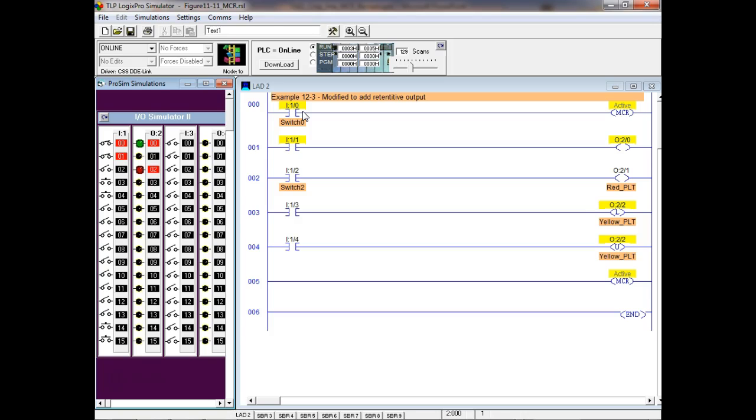So normally, if we're going to use something that cannot be turned off, then we will use a latching relay outside of the PLC, right? Now we could use this right here to turn them off and latch them and unlatch it, right? You understand that? But once it's latched and power fails to my PLC or something like that, I wouldn't want my crane to do what? Drop them out, release a brake somewhere on a motor.